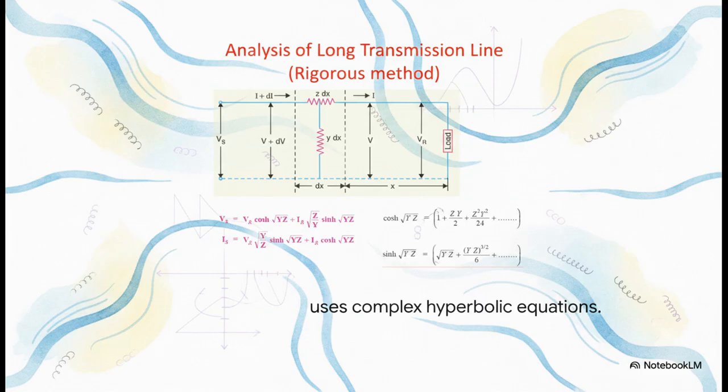Those equations for voltage and current at the bottom incorporate complex hyperbolic sine and cosine functions. Over vast distances, power waves behave almost like high-frequency telecommunication signals. And honestly, these intense, complex formulas are the absolute only way to accurately model that wild behavior.